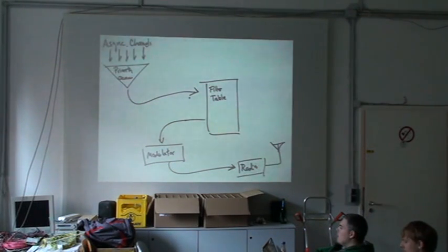But the purpose of the filler table is that in GSM, in any of these digital radio systems, you have to transmit something, even if it's just silence, even if it's just zeros. You have to send something to the digital analog converter. You can't have a discontinuous data stream going into these D-to-A converters, or you start running into all kinds of synchronization problems. You have to transmit something.